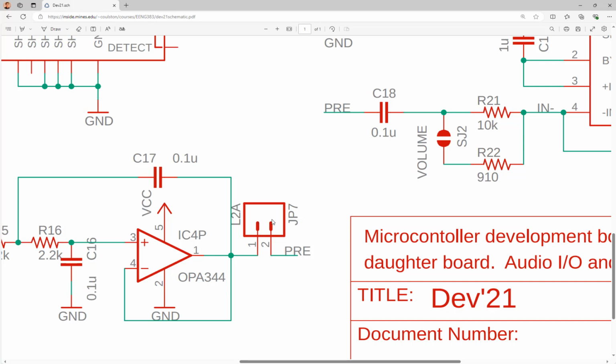So that's two pins. It's going to print two through holes on the PCB without any connection in the middle. You see there's no connection over here. However, this one and this one are connected. The two pre's are connected, but 1 and 2 are not connected. So that's a place you put a little jumper. Remember the little jumper header? You place a jumper on top, so you short the two pins.